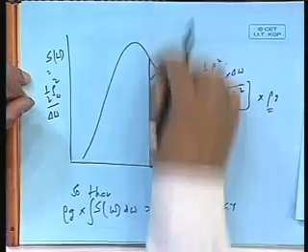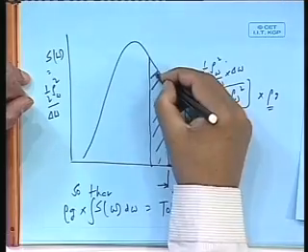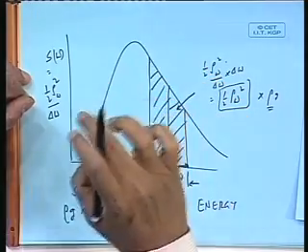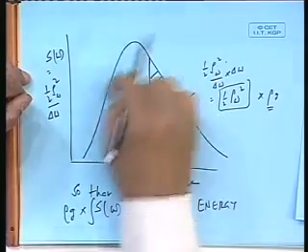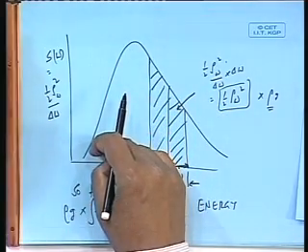And what I am plotting here is the square of the amplitude divided by the frequency band. Why divided by the frequency band? Because by dividing by the frequency band, it makes sure that the area under this becomes the energy of those waves. If I did not divide by the frequency band, the area would not have become so, because it is even higher. I want to make sure that the area under this represents the energy of all the waves. So this is a very standard representation.